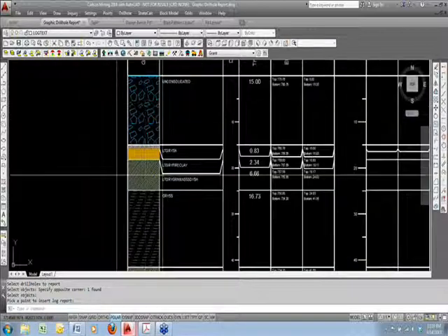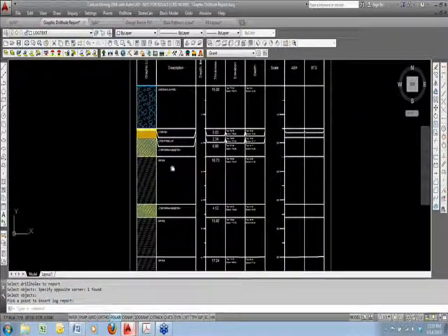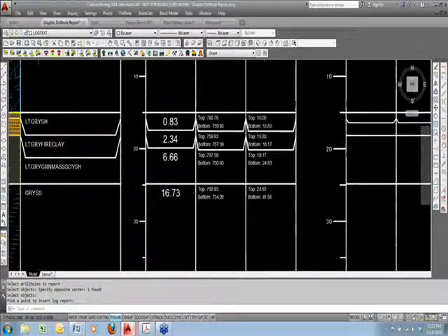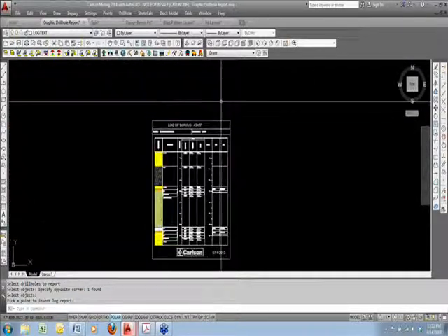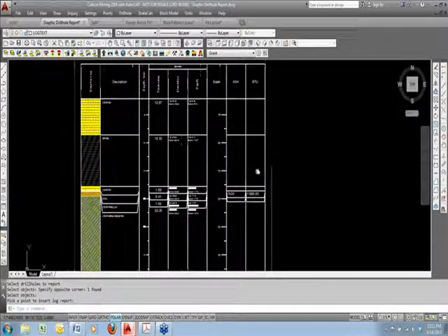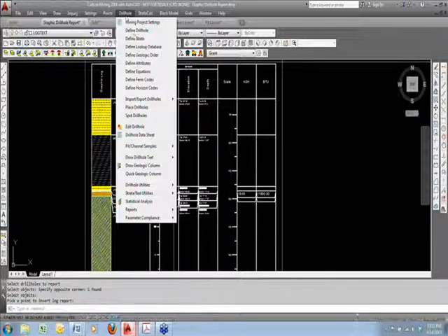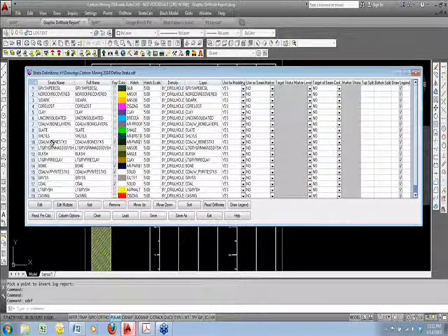The one thing we didn't look at was the hatching and the coloring of the different types of strata and seams down below. They're nicely labeled, and depths, thicknesses, and any additional attributes are showing up on the right-hand side. If this was a coal seam, there you see the ASH and BTU values over on the right. The only thing that's missing to show would be the define strata command, which is a prerequisite to do that report. This just defines all the different colors.